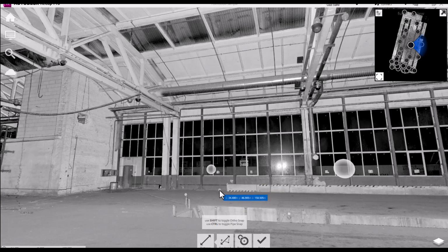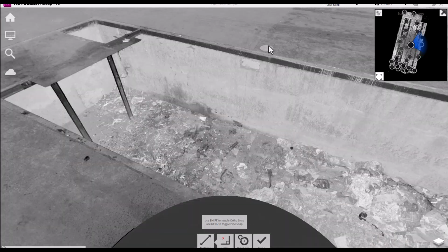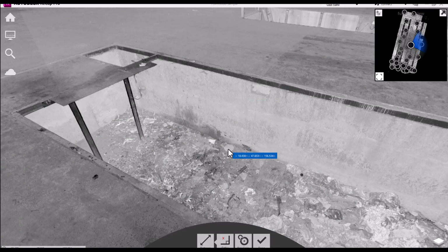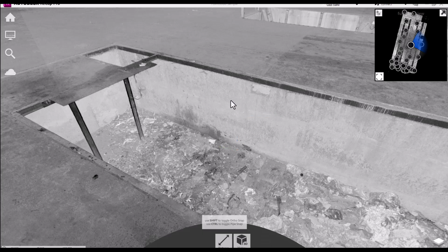Let's say if I want to measure from here to here, approximately it's like 7.346 meters. Then you can measure any area. Like, I want to measure the depth from here. You can see this circle going from here to here like this. I click over here. There is a lot of garbage, which is why it's making these weird shapes, but anyway, it's almost 1.74 meters. So approximately you can capture the depth in order to start your modeling.